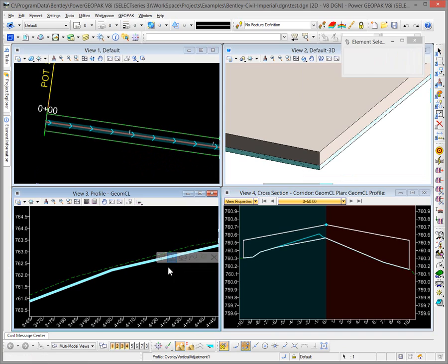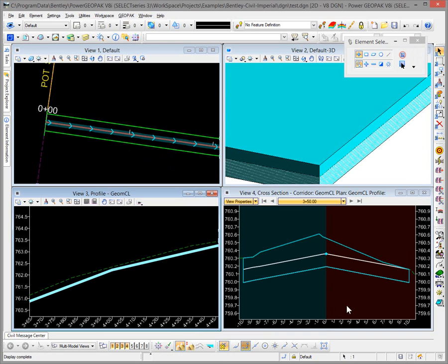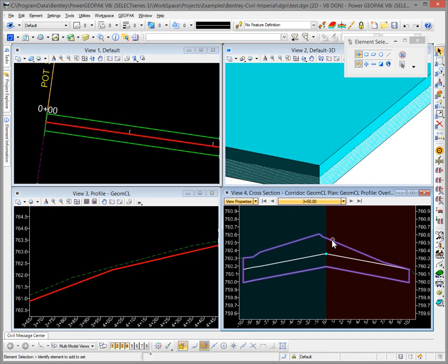And so we're going to set this profile active, and you can see it would come from the bottom up. The lowest critical point actually fell over here on the right side. So minimum milling gives us now, this is our milling configuration, and all then of our overlay, our new component, is down here below ground.